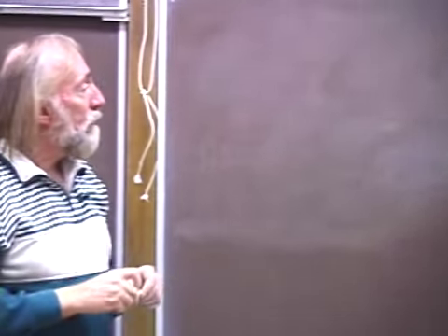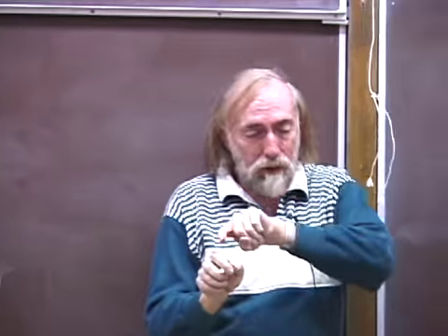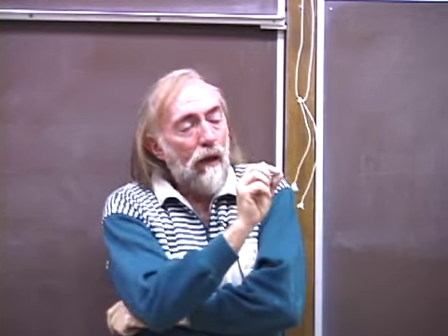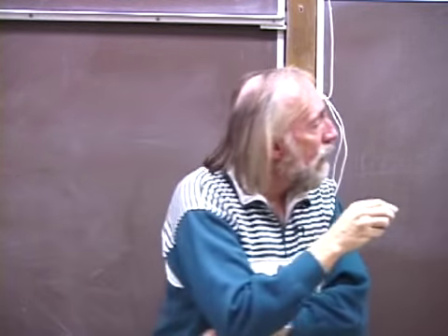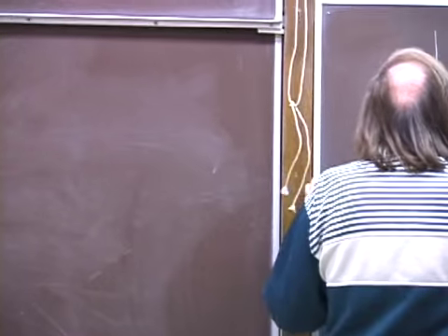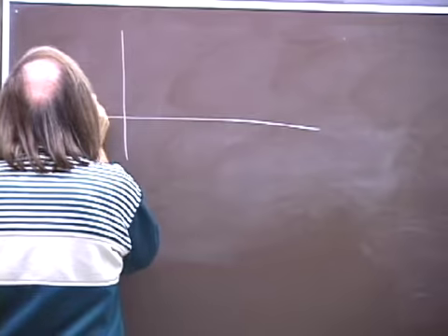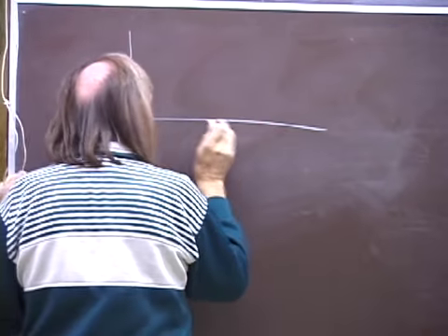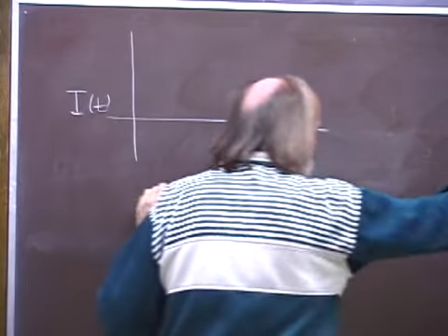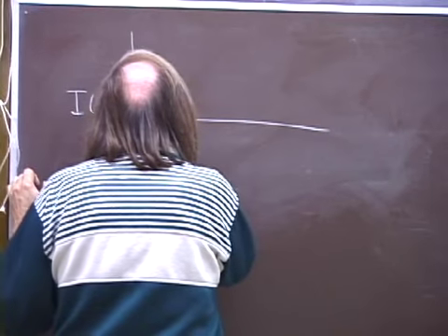Now this light beam consists of individual photons. Each photon comes into the photodiode, and if the photodiode has perfect efficiency, another little issue that a theorist always assumes, perfect efficiency, and the experimenters worry about the efficiency, then each photon comes in and it generates some electrons that flow through and get measured by a circuit. And so I of t consists of pulses of incoming light intensity, one pulse associated with each photon.